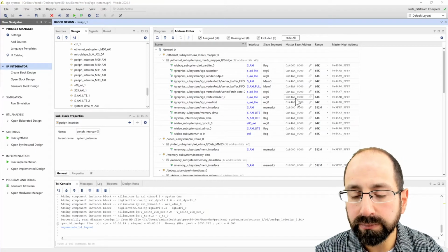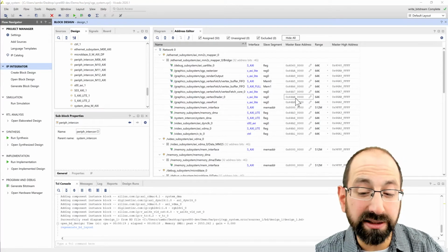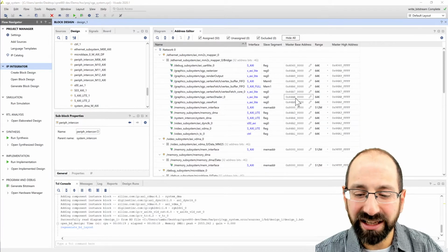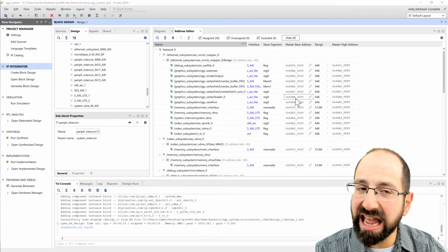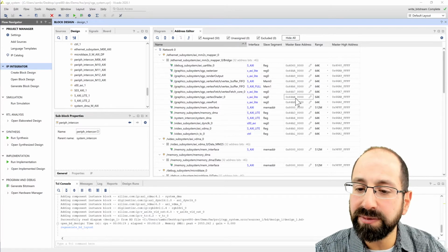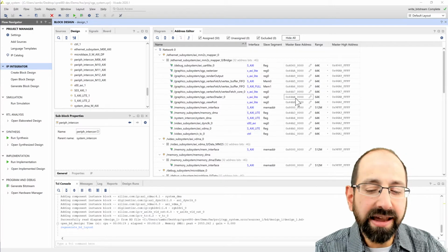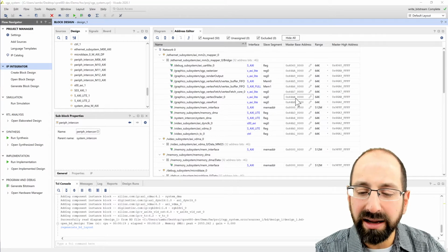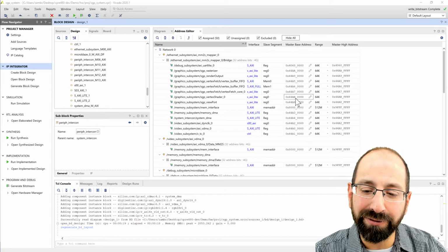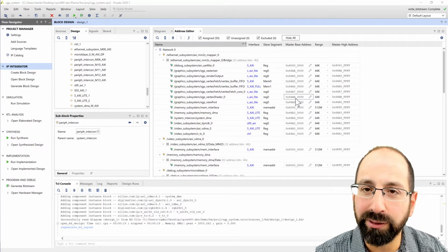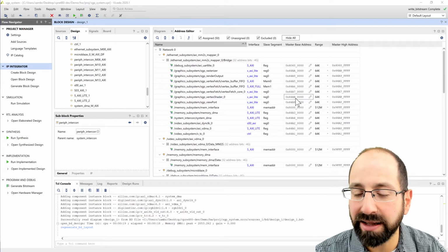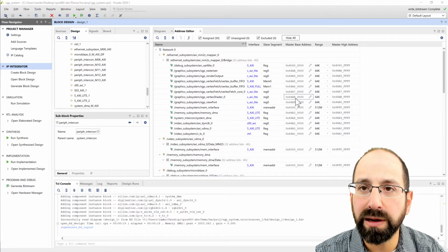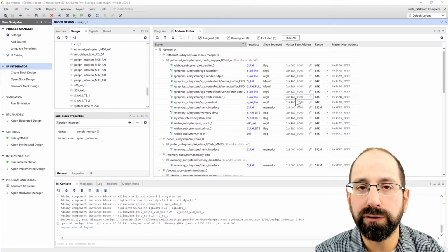And that's something that's hard to test in simulation because you're not simulating the entire system in that sense. And it's a little hard to test that it's happening on the board. That's where the ILA comes in, where you can start to actually check that. It'll be easier to check that via software, to have readable and writable registers, and to just poll those registers in software and see what the values of my configuration registers are. Am I getting debug information back out that makes sense to me? But different approaches may work depending on your team's personal workflow.